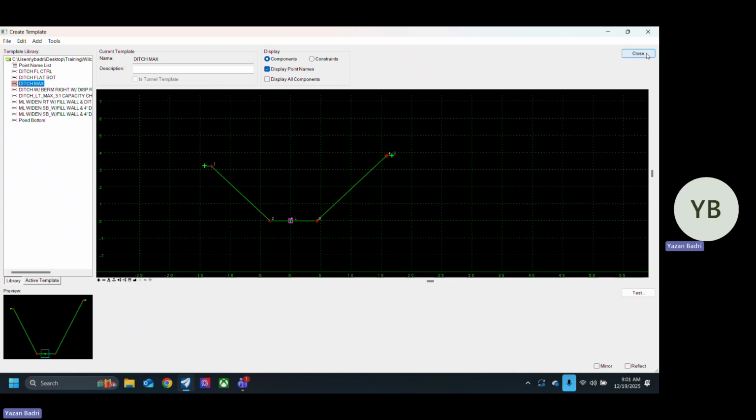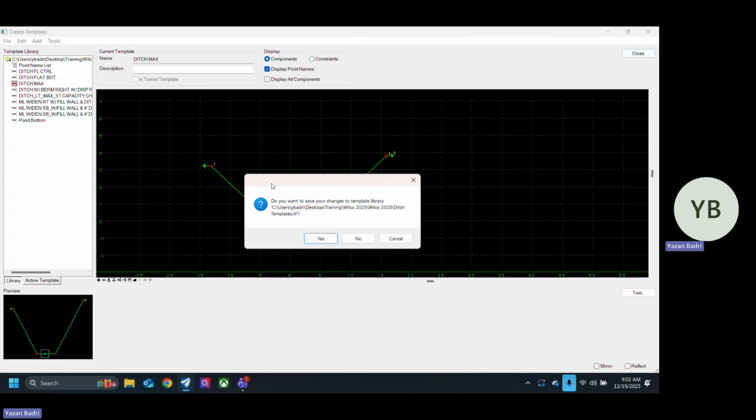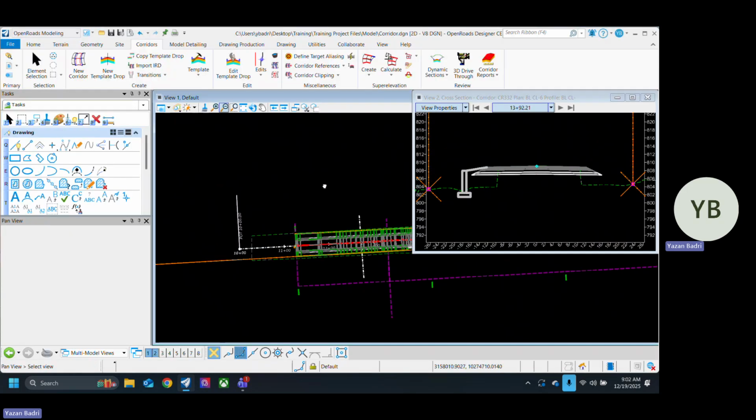I also have one with the reinforced backfill behind the retaining wall. I also have that modeled in the template, and you know how the width of it depends on the height of the wall, depending on the geotech report. So I have that link between the two, where if it's this height multiplied by 0.8 width, if it's this height multiplied by 1, for example. So I have different rules for that. All right, I think that's enough for display rules.